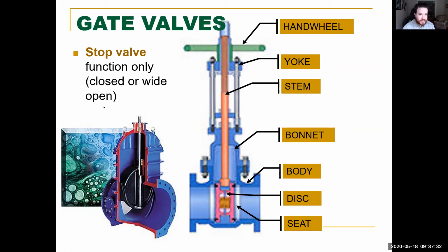All right. So if you have two gate valves in series with each other, before it goes off to, let's just say, a system. And this is coming from a pump. Both these valves right here are gate valves. When they're in line with each other like this, that's when you can use one of them as a throttle, but only one of them can be the throttle valve. This one will be the throttle valve, and this one will be the stop valve.